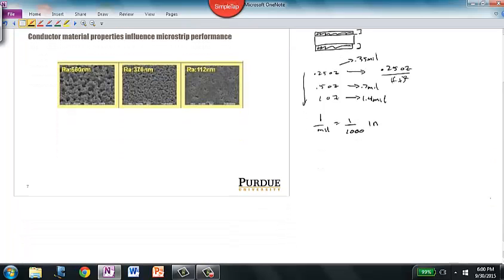One negative effect of lots of copper is what's called a sidewall effect. If I make extremely thick copper traces, what ends up happening is, if this is copper and this is copper, I get a parasitic capacitor right there. I also get a parasitic capacitor here and a parasitic capacitor here, where I can minimize that effect with thinner copper traces. The capacitor here and the capacitor here are effectively eliminated because there's not enough cross-sectional area to support them. So thick sidewalls can negatively affect circuit design because of these parasitics.